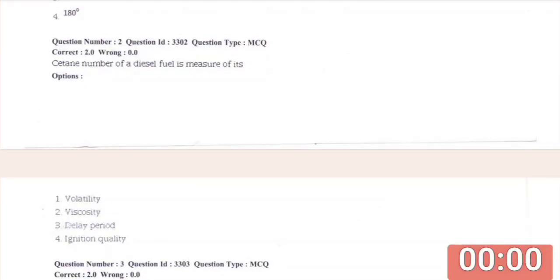Basically, the cetane number of fuel is defined by finding a blend of cetane and isocetane with the same ignition delay. Cetane has a cetane number defined to be 100, while the isocetane measured cetane number is 15, replacing the former reference fuel alpha methyl naphthalene.